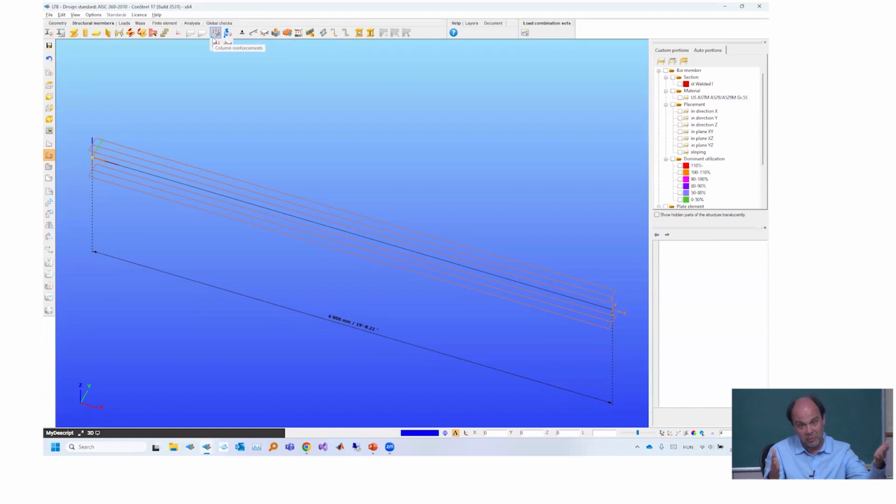Typically, if you want to use the critical moment, we find the biggest bending moment and multiply it by 4.41. Actually, the question can come: what if we don't multiply the biggest one, but another? Then we have another critical moment, and we can have as many critical moments as there are points on the structure. We can even have 0 if we select the 0 at the end and multiply it by 4.41. That clearly shows that the critical moment itself is not necessarily a good measure, because it refers to a certain point. If everything is uniform, it's fine. But if it's non-uniform, like a typical structure, it's not a standalone value; it also matters where the critical moment is. That's why we will see that we are not using the critical moment itself, but something more general.